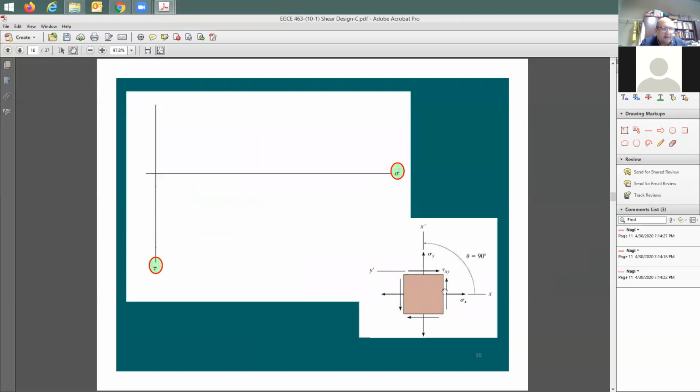Here is the general stress element with all the stresses on it in terms of normal stresses on both faces and some shear stresses. On the x-axis, we're going to put the normal stress, sigma. On the y-axis, we put tau, the shear stress. Now, next to that, we need to plot 2 faces. So each face is going to have a point on the circle.